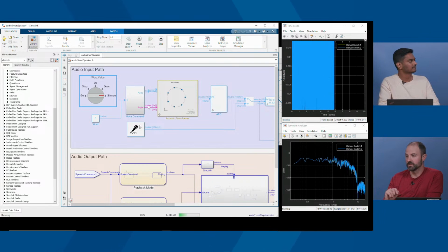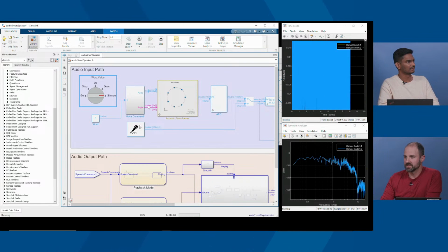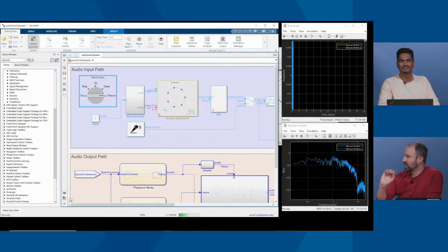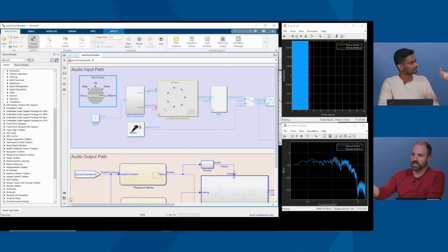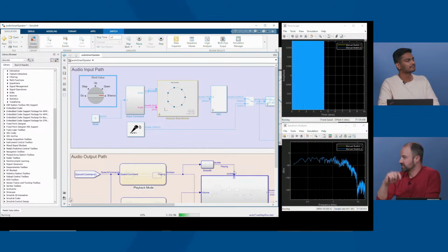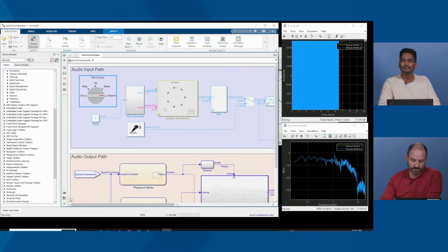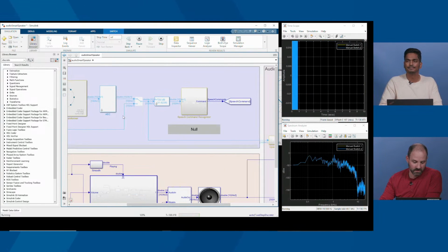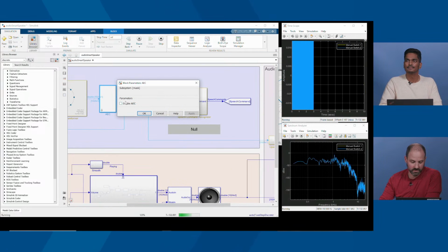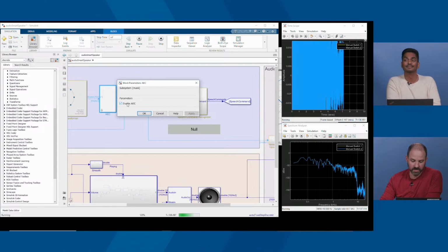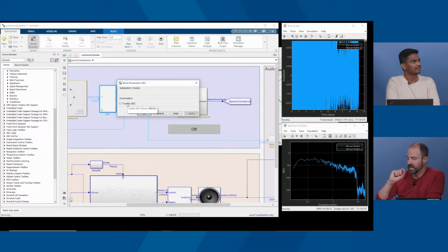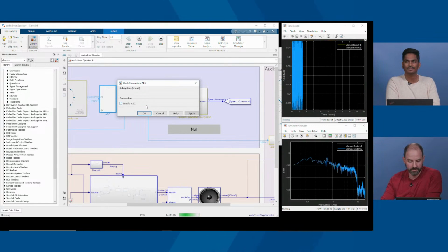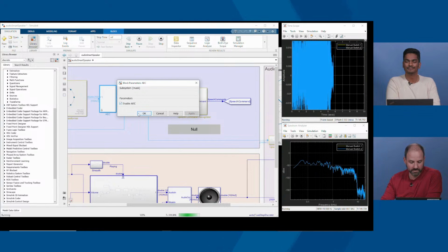So now the audio that we're hearing sounds a little funky. It sounds almost like it's far away, right? That's because it's playing back into the room, and then the microphones are recording what's playing back into the room. So let's try turning on that AEC, see if I have it dialed in correctly. Yeah, so when the AEC activates, it cancels out the playback audio. So I'll turn that off and on one more time. You can hear the difference.